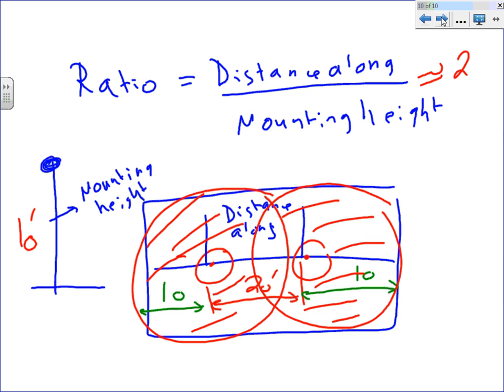It gets complicated. The nice thing about Visual is when you build your room, guys, it asks you about three factors: wall reflection factor, ceiling, and floor. And if you don't know these, there's defaults. So say if you don't know, no problem. Here's a default that we normally use. And it defaults the reflection factor when you do a calculation, especially indoor.